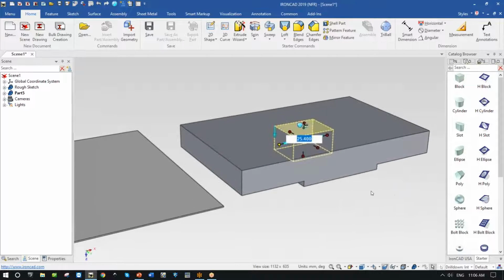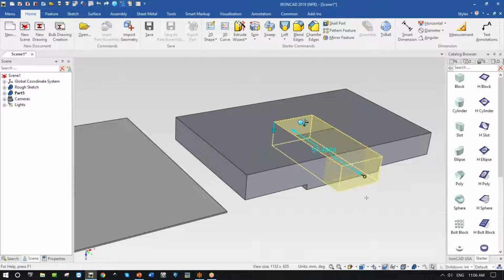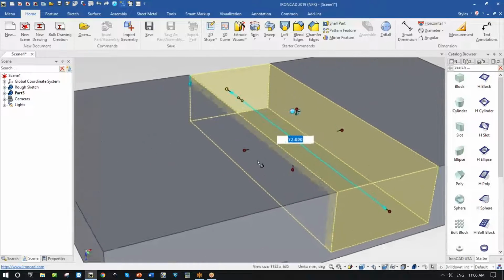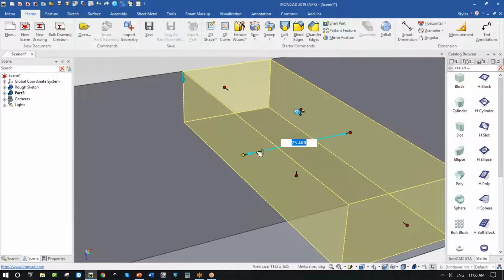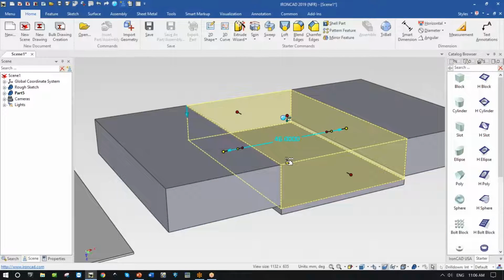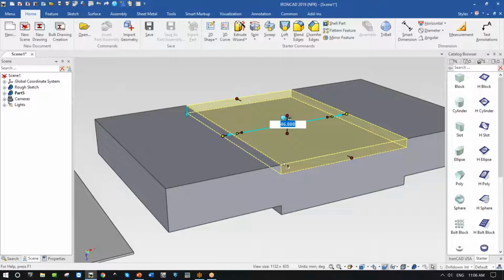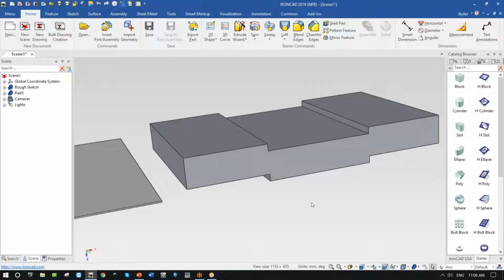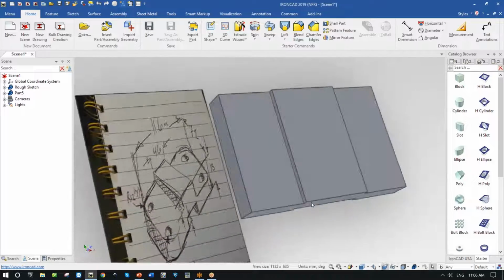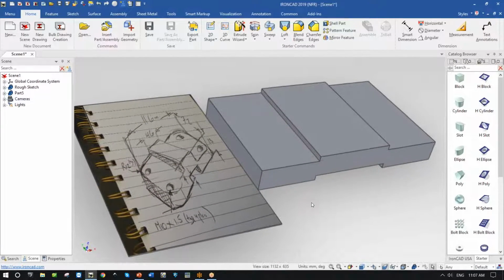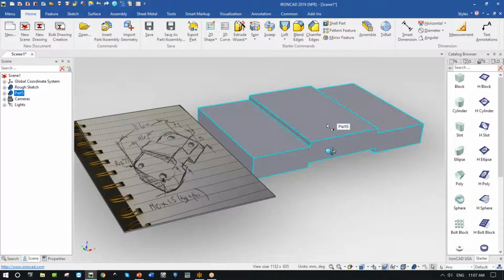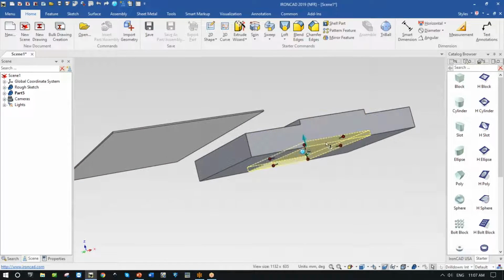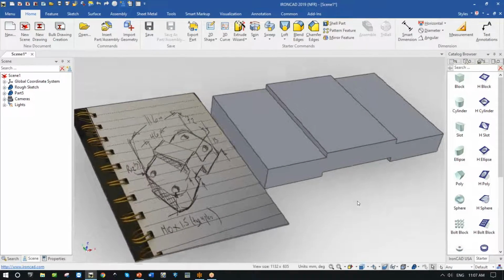Oh, so now I'm cutting with this, come out to the front. How do I do that? Shift, grab the front, find this back face. And then as I zoom in to see, well, how wide should this be? Oh, this should be equidistant, 46. How deep? Well, we had said it should be exactly 3 millimeters deep. There you go. So I'm creating this part without having to do any sketching at all. I used a positive part on the top and a negative shape on the bottom.